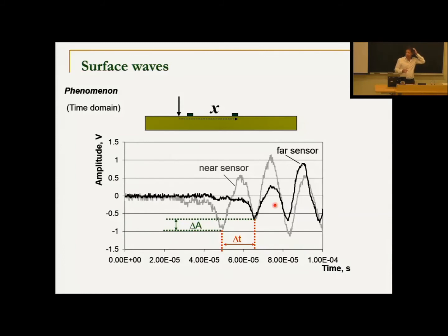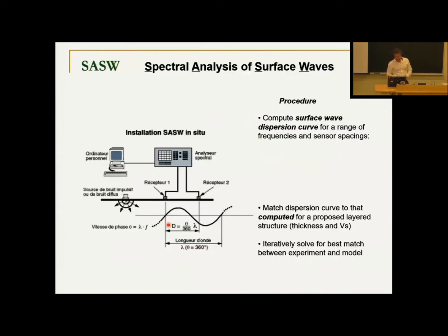And this is a velocity, so the time is related to elastic constants and density. Amplitude loss could be due to energy dissipation and so on. So these kind of fundamental measurements that we could try and relate to the characteristics of the material, either attenuation or velocity. Okay? But this is a rather simple approach. I'm introducing this concept because it's very simple and to help you understand.